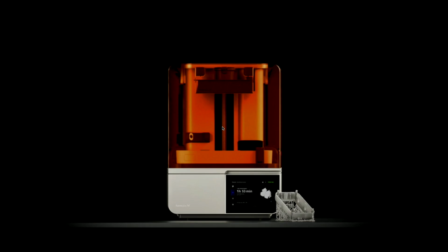So for the process for the metal casting, what we did is to use a SLA type 3D printer using wax material. And wax was chosen because it allows for high precise printing and can be directly used as a casting mold.